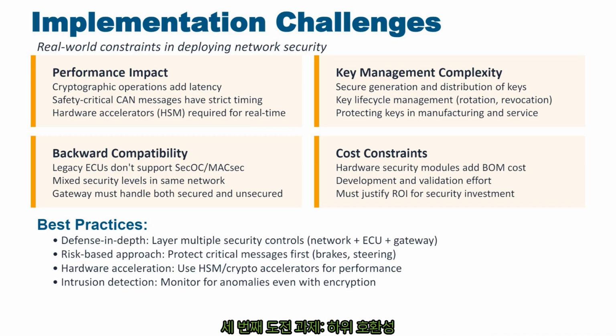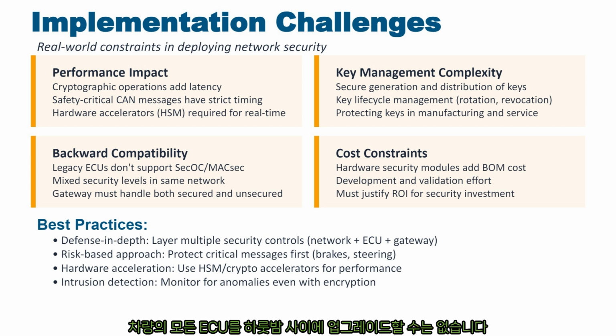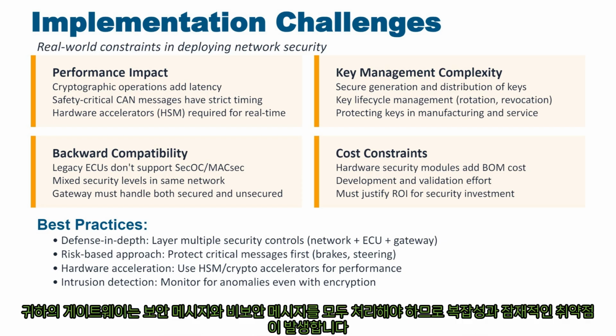Third challenge, backward compatibility. You can't just upgrade every ECU in the vehicle overnight. Legacy ECUs don't support SecOC or MACsec, so you end up with mixed security levels in the same network. Your gateway has to handle both secured and unsecured messages, which creates complexity and potential vulnerabilities.